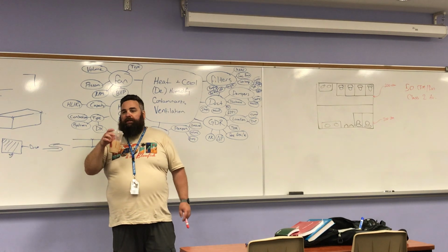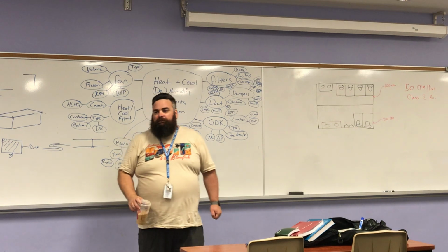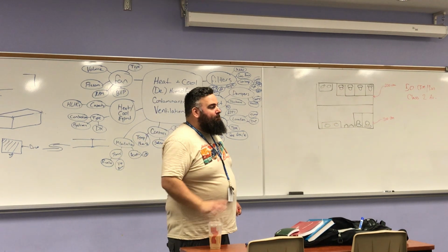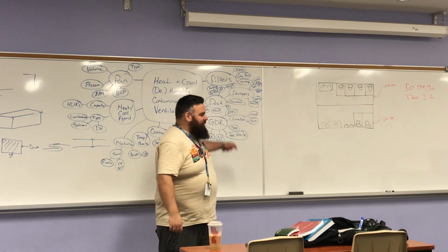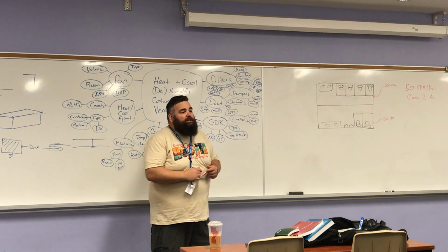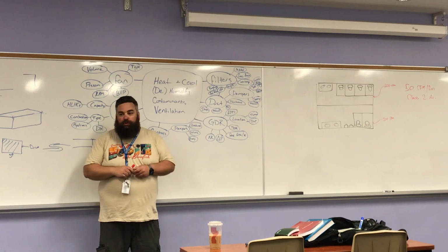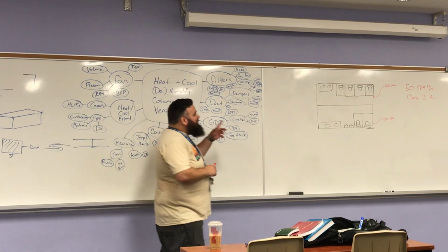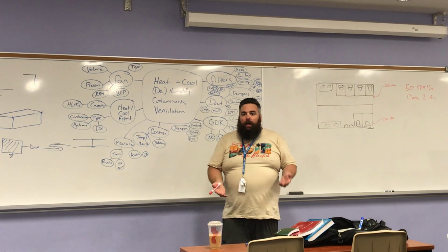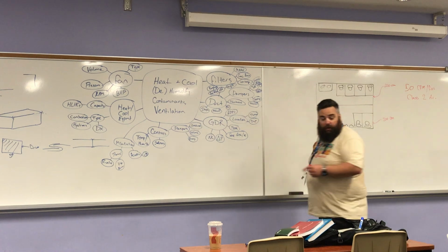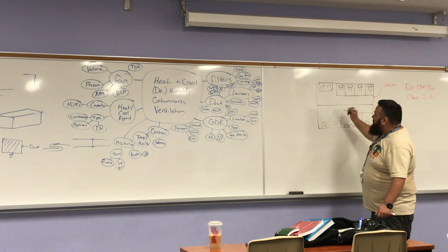Now, what do you think the next step is? Return? Your return or your exhaust? So the exhaust, and you're probably talking about my inlets. I need to think about my grills, diffusers, and registers. In this case, we're looking at grills or exhaust grills. Okay? So I know I want that, but I also have to consider my distribution pattern. How many and where am I going to put them? Am I going to put one big exhaust grill here?